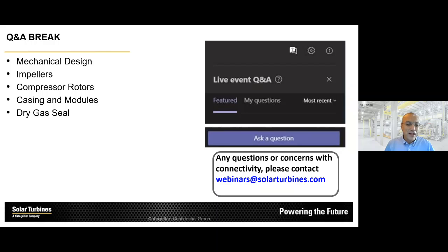This is actually an excellent question, and I will talk a little bit about software in a later section. But essentially, Solar has a software that is called TurboCell. But without trying to throw around names, the key piece of software that you use to evaluate compressor performance uses an equation of state, which is something I will explain later. And Solar uses as a standard the Redlich-Kwong equation of state, but we have the capability to also use a number of other equations of state depending on the exact situation.